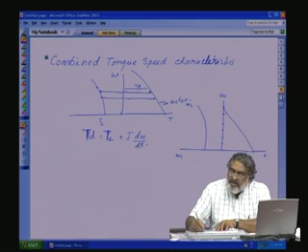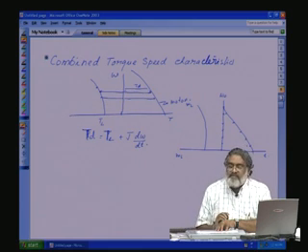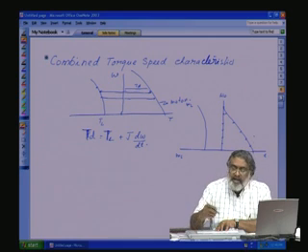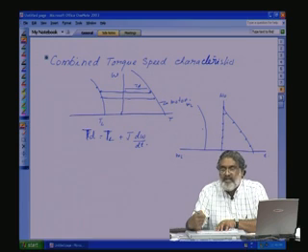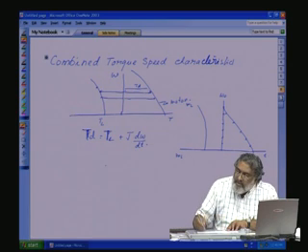At various points, measure the time and omega, and approximately at this point and time you can find out d omega by dt. The motor system is under no load at various speeds, so we know at various speeds what the driving torque is. So, this driving torque is the no load torque.